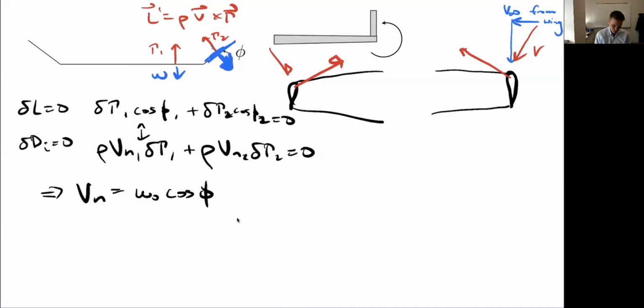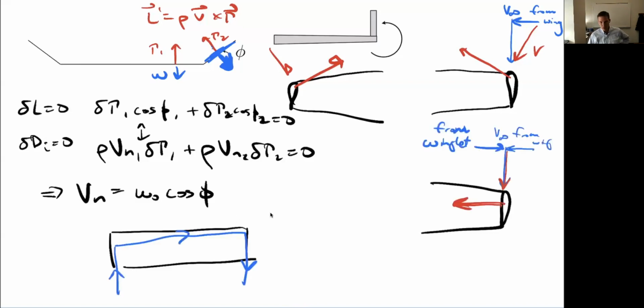That's a non-intuitive result, perhaps, right? Because this actually means the winglet does not generate induced thrust. Total velocity is now just downward. So the perpendicular force is, sorry, not downwards, it's perpendicular to the winglet. No induced thrust. So how could that be better, right? I mean, we said that this is optimal, but clearly having some induced thrust is better than having no thrust.